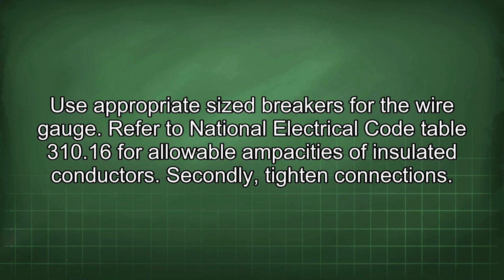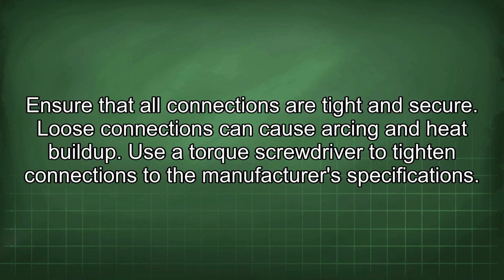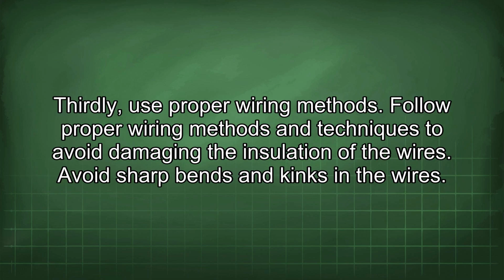Secondly, tighten connections. Ensure that all connections are tight and secure. Loose connections can cause arcing and heat buildup. Use a torque screwdriver to tighten connections to the manufacturer's specifications. Thirdly, use proper wiring methods. Follow proper wiring methods and techniques to avoid damaging the insulation of the wires. Avoid sharp bends and kinks in the wires.